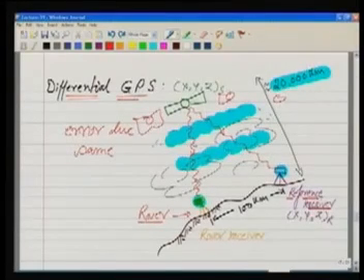So far we know that all the errors due to satellites and due to atmosphere, occurring at the rover and at the receiver, are same. But the important thing here is we know where our reference receiver is. Well, we do the computation now.